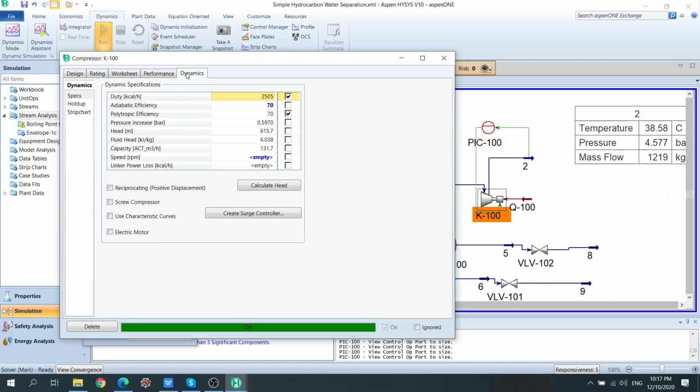What if we just compress it so that it can be converged to stream number 8? Stream number 8. Because they are both hydrocarbons. But this is gas, this is liquid. Yeah, but we compress it to liquid. Is that possible? You compress this into liquid. That liquid change is not going to happen in the compressor because it will break your compressor.